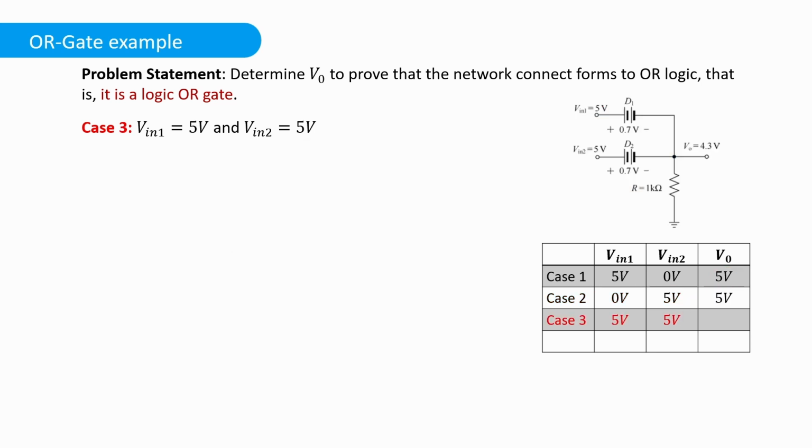In this case, we can see that we have an input voltage of 5 volts at both terminals. So we can say that there is this common voltage source, right? And it is 5 volts. And then it is grounded, or you can connect it over here as well. So now what happens is that we have an input voltage at both terminals. Once again, the first step is to see if the diode is in forward bias or reverse bias condition. But since the circuit is already obvious to us, it is constructed in a way like this. So we know that this will be in forward bias.